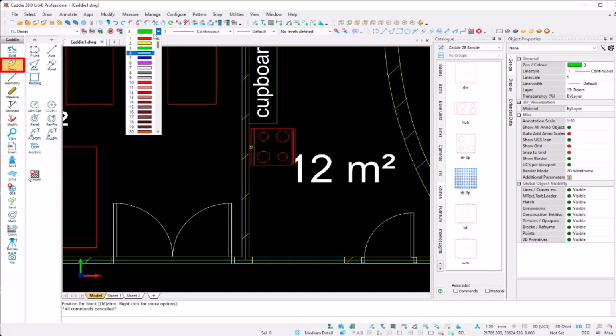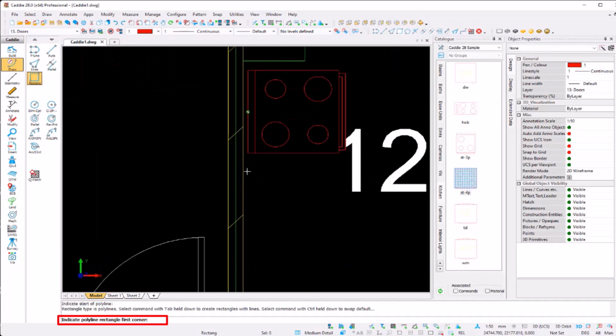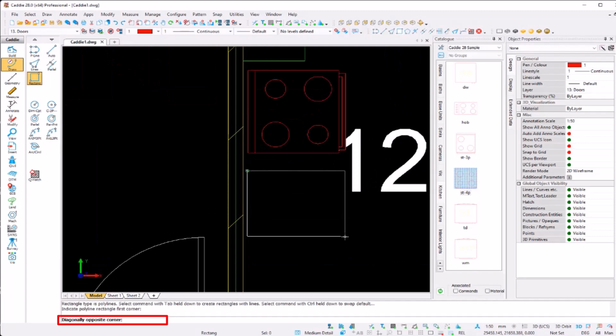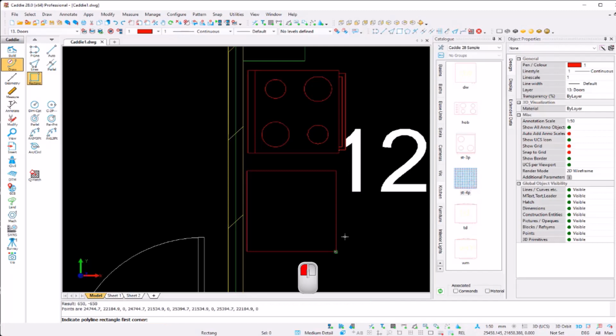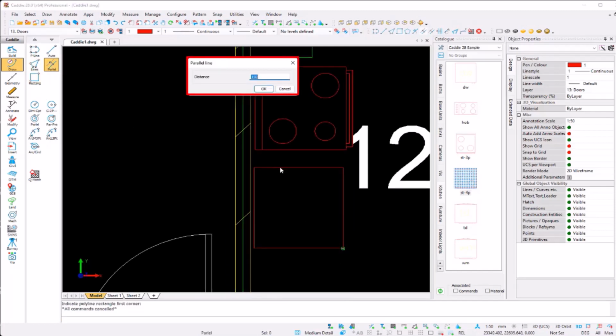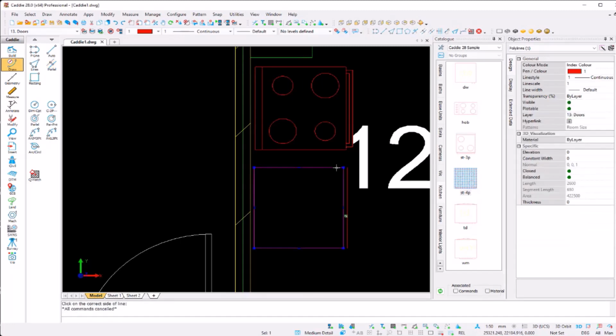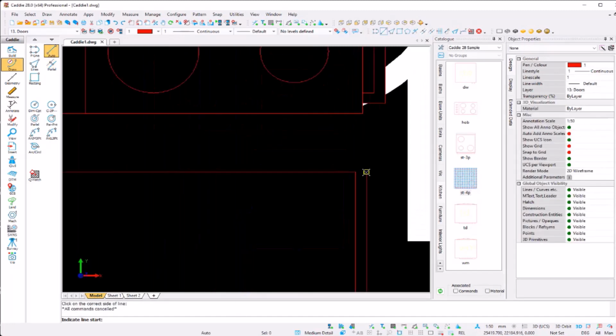Let's go back to pen number 1. As I showed you, very straightforward. Select a rectangle. For that matter, you can give it a size. Normally it's about 600 by 600. So let's make it 650, minus 650. Let's enter. Let's create parallel for the front of the stove that's presenting. Let's make that 25. So don't assume that you need to have a symbol for it. Create your own symbols.